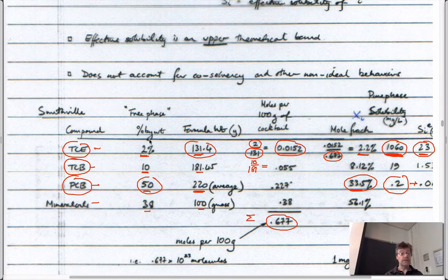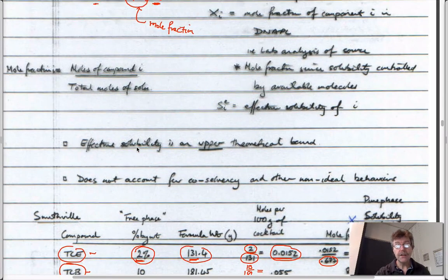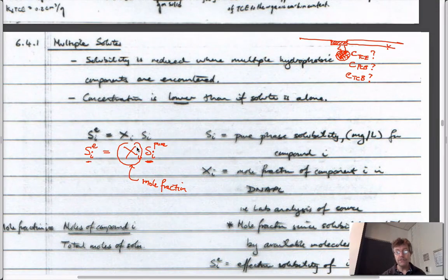Big difference, right? And so we need to be aware of what the relative proportions are upstream. And so when we're doing these calculations to look at the motion of this downstream, then the initial starting concentrations, as we start at the upstream location of this core plug, which is what we've been using to calculate our transit downstream, the initial concentrations that we have at this point for TCE would actually be 23 ppm, which is the same as milligrams per liter.